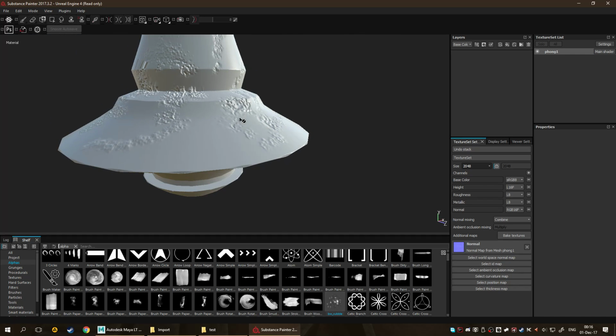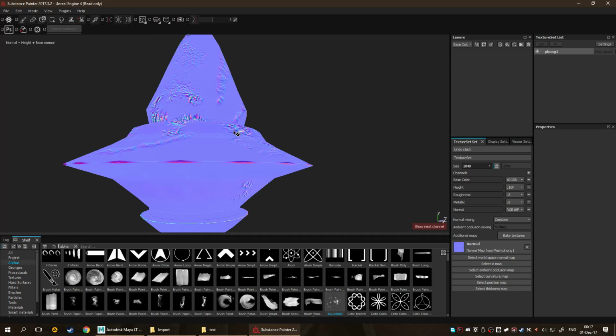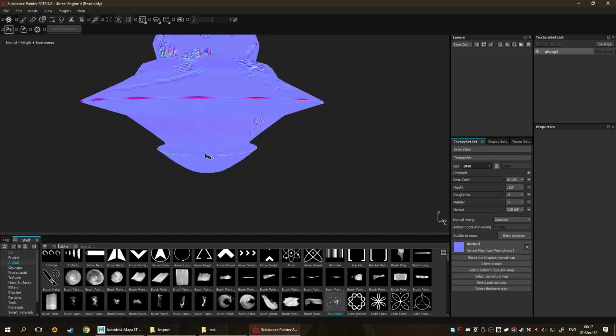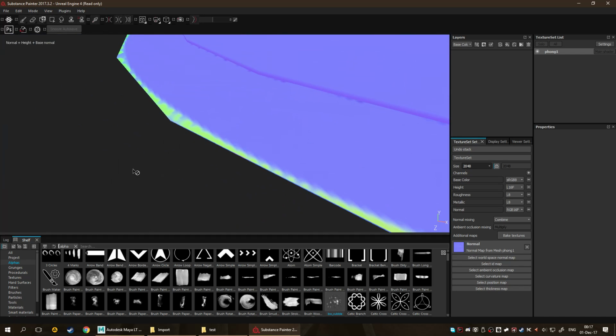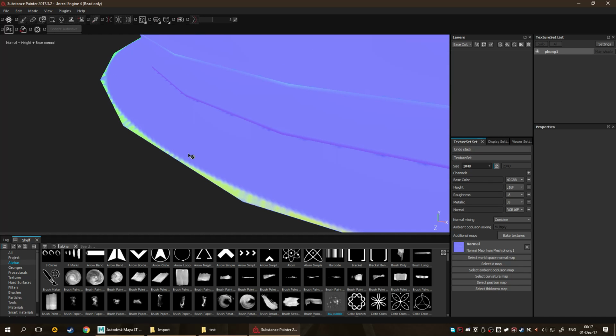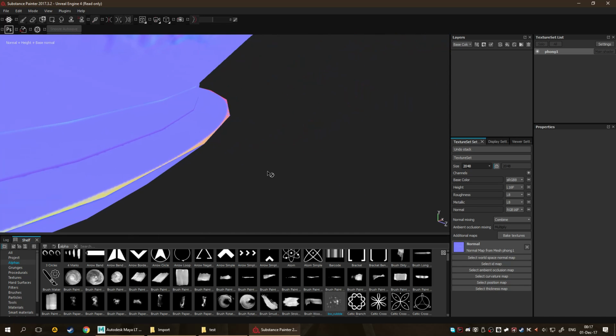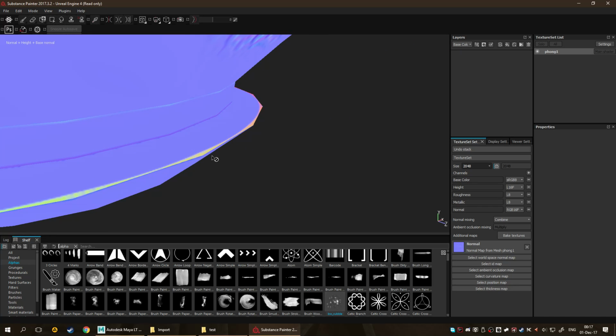However, there's one more thing we did. If we take a look at our UV map over here, there's also problems in the corners here where we have not a close enough approximation. This blue part, by the way, you can tell clearly it's round, and this is our high poly model. Our low poly model is sticking out too much. And remember, I told you, when you smooth something, you lose volume on it.